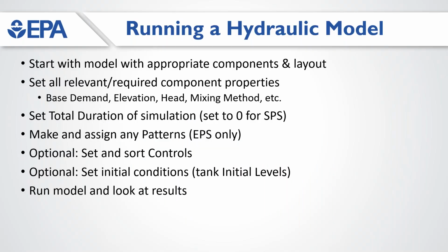Here are the basic steps to run a hydraulic simulation after having built the model. Each component needs properties set through its property editor. These values and properties depend on the system and the type of simulation. Each simulation needs a total duration set in the time options to determine if this is a SPS, single period simulation, or else how long the EPS will cover.